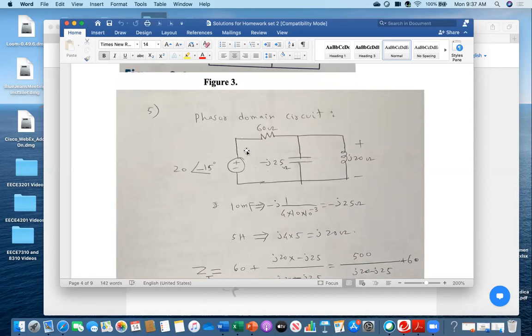So now you see, by looking at this circuit, first you find out the total current. What is the total current flowing through here? If you can find out the total current flowing through this branch, then look everybody, that current is going here. After coming here, some portion is going through this one, something is going through this portion. You have to find out this current. That's all. So once you can find out the total current flowing here, you apply the current divider rule. You all know.